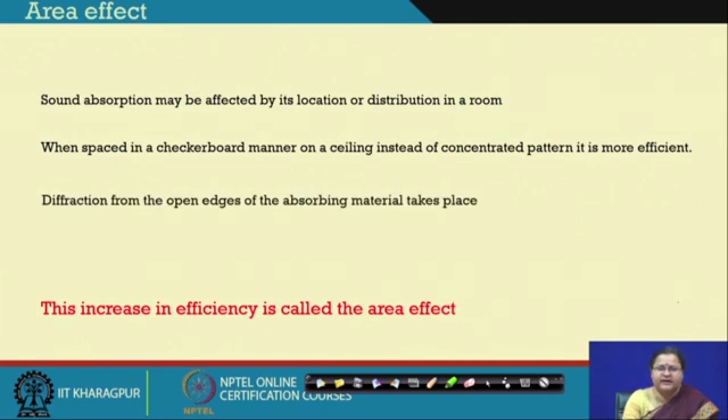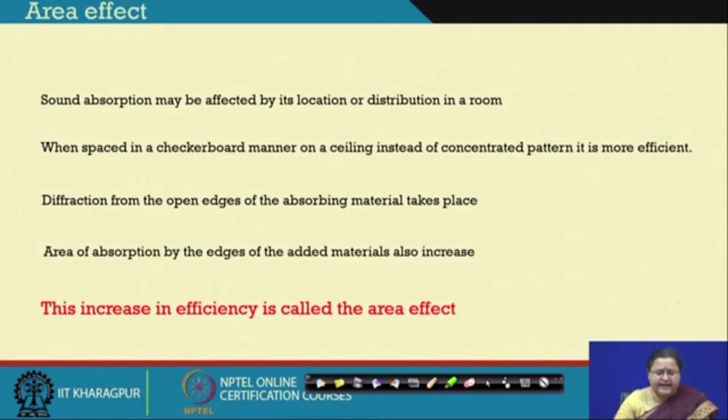What happens when you put in the absorbers is that diffraction from the open edges adds to the absorption, and the edges are also absorbing the sound to some extent. So, the area of absorption by the edges should be added while making such calculations, and this increase in the area increases the efficiency of the absorber, and that is called the area effect.